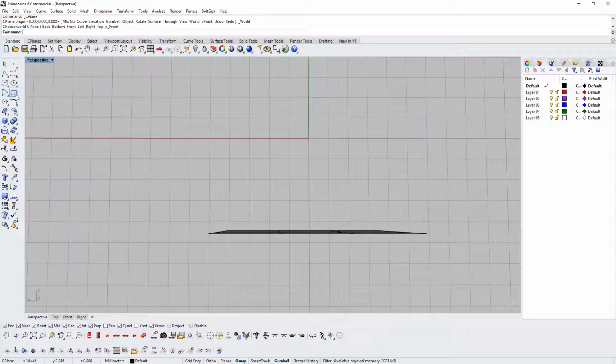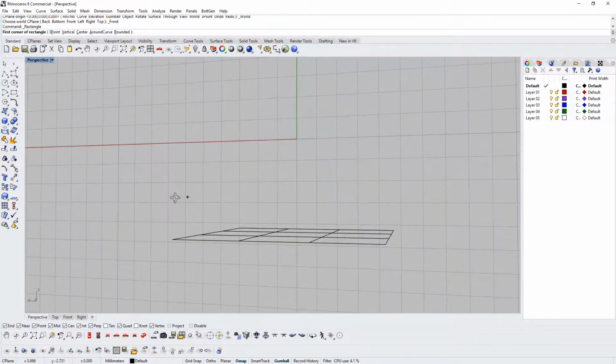And what we're going to do is draw a cube, and for our measures, we're going to click that corner, hold down Shift, point it in that direction, hit Tab, and type 1.